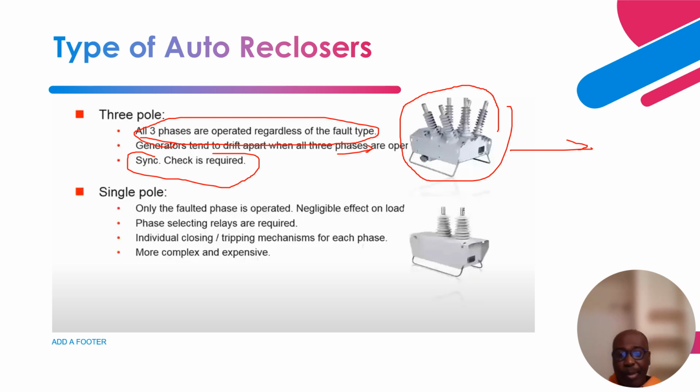So there are set points. Let's say 80% of the voltage is considered to be the required voltage for closing in, and 20% is the voltage that is considered that operation will not occur.